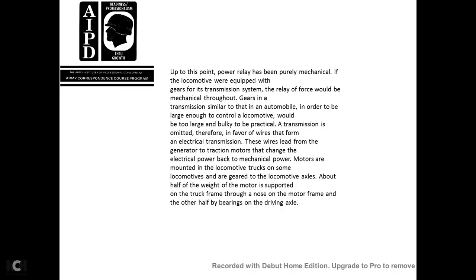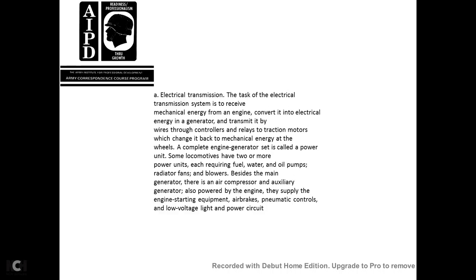Motors are mounted on the locomotive trucks. On some locomotives they are geared to the locomotive axles. About half of the weight of the motor is supported on the truck frame through the nose of the motor frame, and the other half on the bearings of the driving axle.